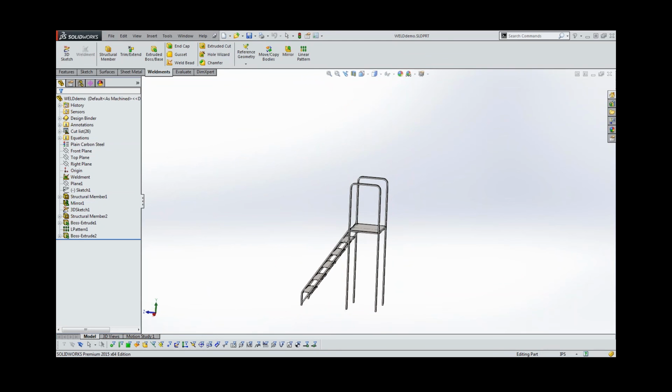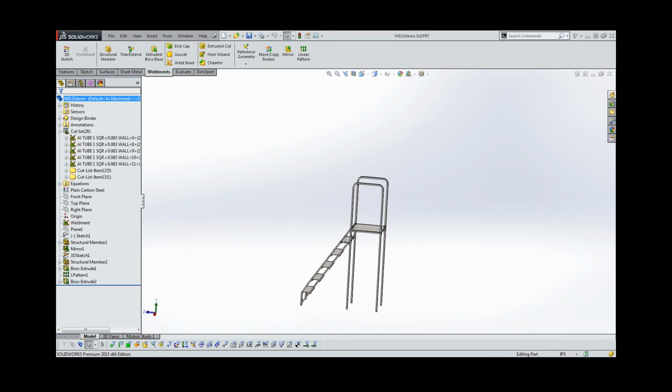And I've done a lot of handrails, and it's generally pretty close. I've had shops who use their own software for calculating the stretch and whatnot, and it really comes down to some shop specific settings or settings to their dies. But a lot of software out there now can take the SolidWorks model, or you can save it out as a solid and import it into the bend software, and for the most part it comes up just right on the money.